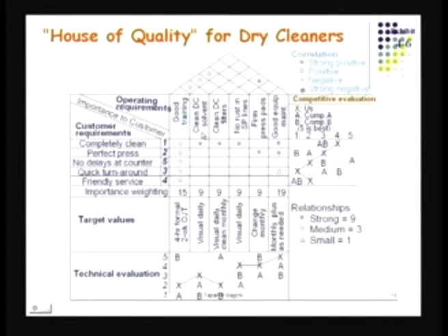We require good dry cleaning fluid. We require good filters in the system. There should be no rust in the different solvent lines. The press pads should be firm, and of course, equipment maintenance must be top notch. If you do these things, you are going to be able to take care of these requirements.